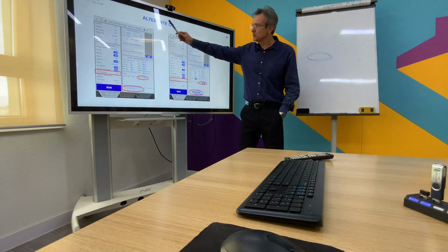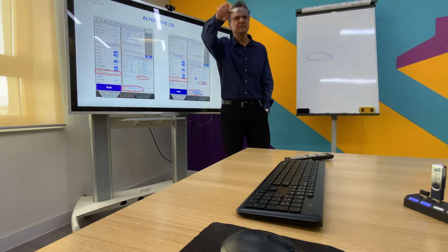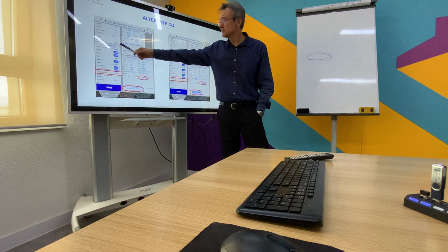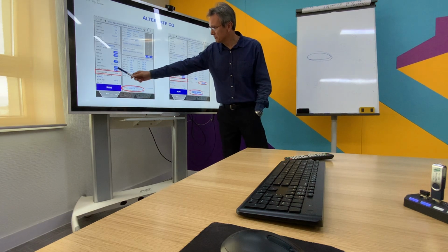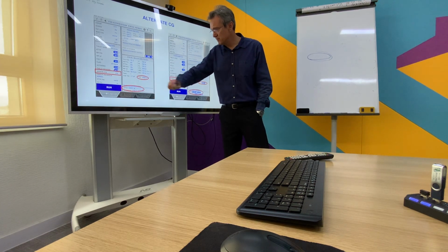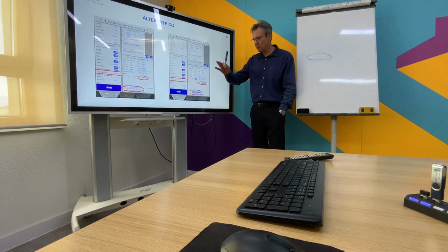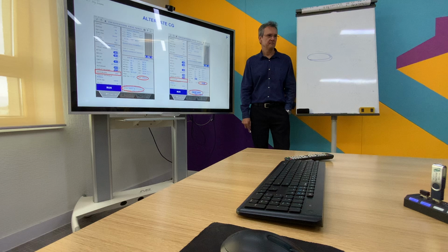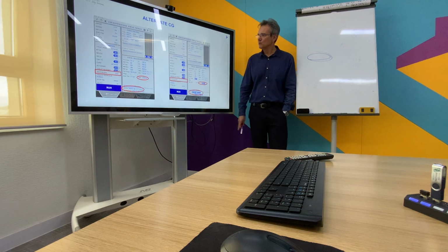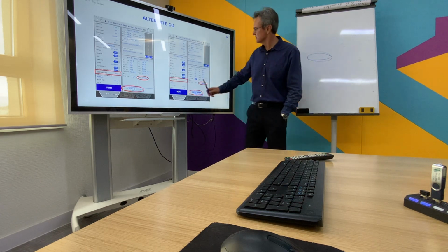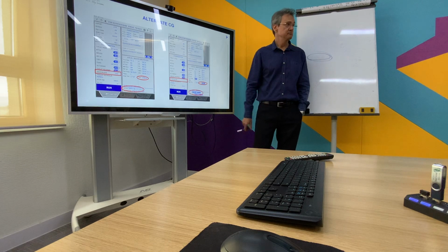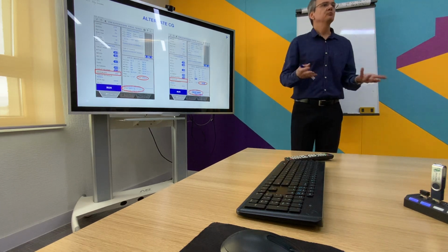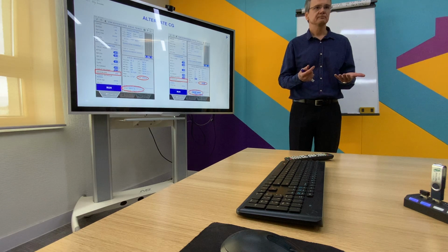For the same condition, same airport, Tashkent, 40 degrees, it's a high airport. With normal CG, standard CG, we may take off with almost 55. With alternate CG, 56. With Takeoff 3, no flex. Takeoff 3, flex 42. That's the advantage of getting the alternate CG.